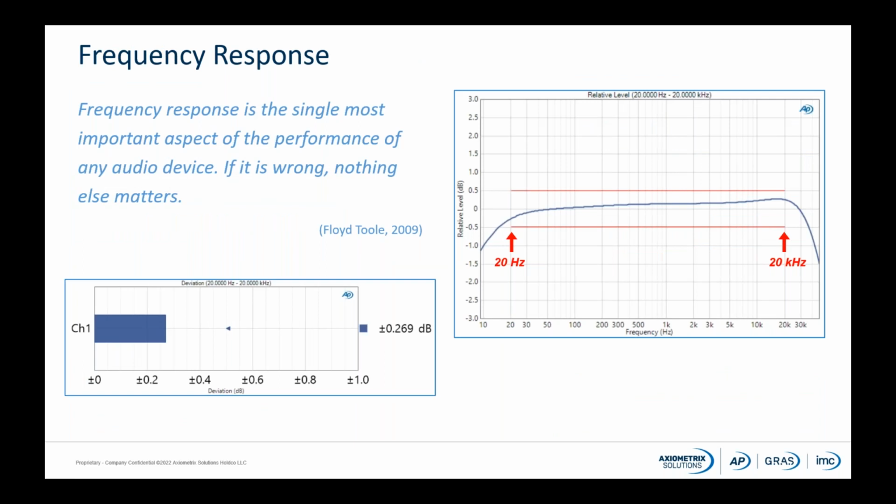Frequency response is probably the most telling measurement result. We can use stepped frequency sweep, continuous sweep, multitone, and transfer function measurements in closed loop or open loop configurations to show us the response as well as other results.